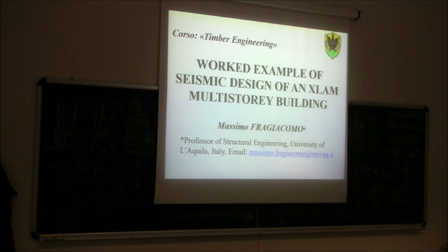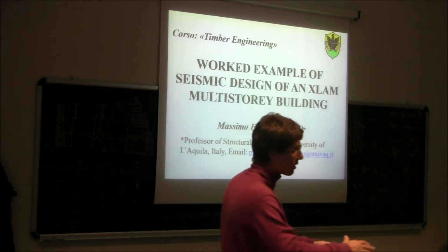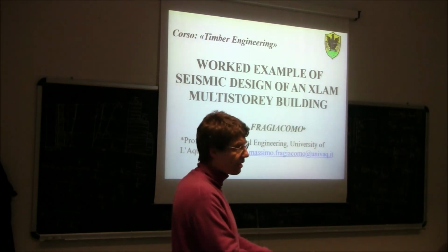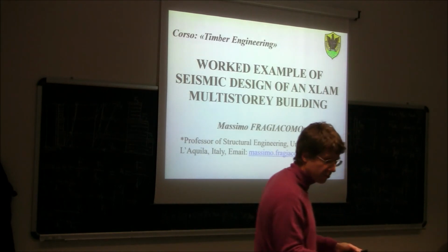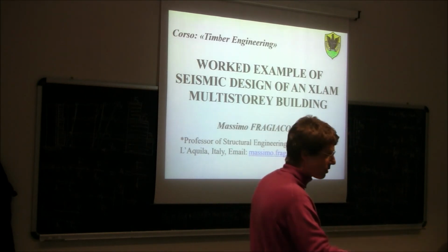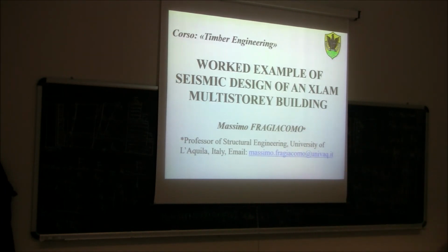So for this one, I would like you just to calculate in this work example the seismic forces, then to distribute the seismic forces at a certain level between the walls, and then to design one wall. Just to have at least once, after you follow more courses on seismic design of course, the experience to see that you are able to follow step by step the different verifications. So I'm not asking to design the whole building. I'm asking to take a small building like this.